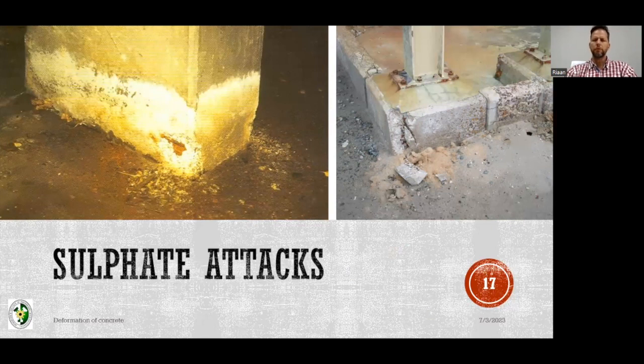So if your concrete has a high sorptivity or a very high permeability, or what we term an oxygen permeability index, it becomes a problem because it is almost like a sponge. As soon as you wet it, the water gets sucked into the surface. That is capillary suction, diffusion, there's a bunch of them. The water goes into your concrete, and whatever is in the water gets transported through what we call these transport mechanisms. So your capillary pores and cracks become highways for gunk to go and damage your concrete and your reinforcement.